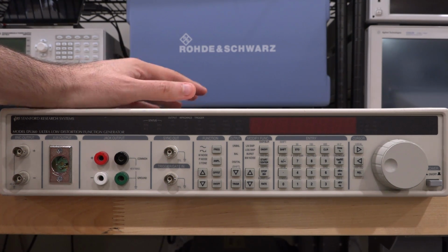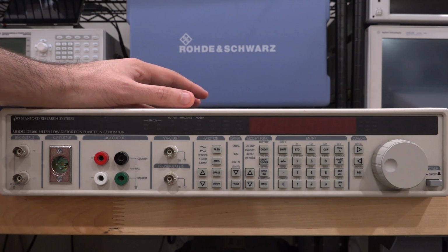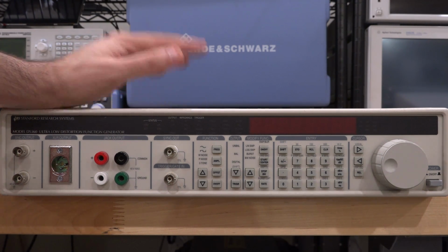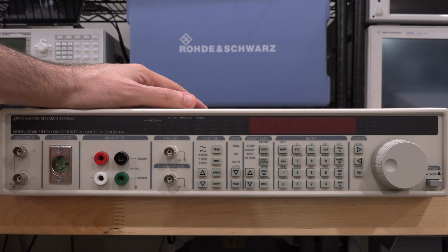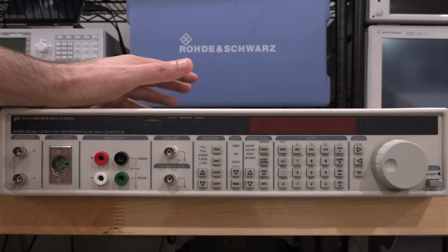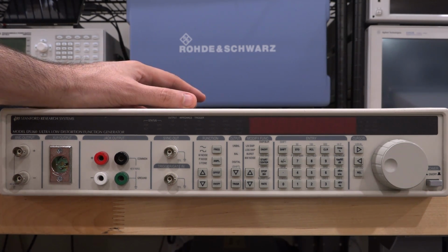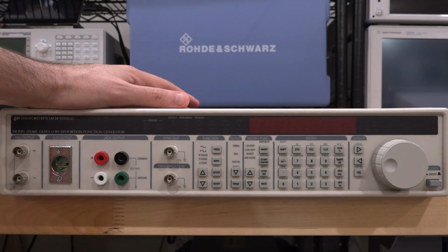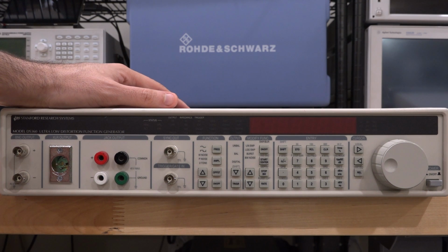Now keep in mind that a normal arbitrary waveform generator may have a THD of, let's say, 50, 60, which already would be very good, but this thing is over 110 dB, so it's extraordinarily clean. It doesn't do much beyond that. It does have some other functions like ramp and pink noise generations and even two-tone generation, which is fantastic. If you ever work on audio equipment, this is kind of the instrument you need.